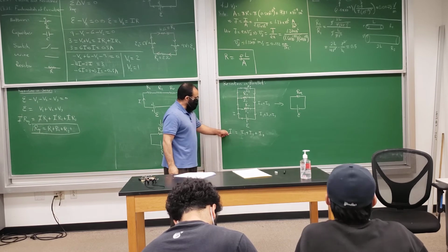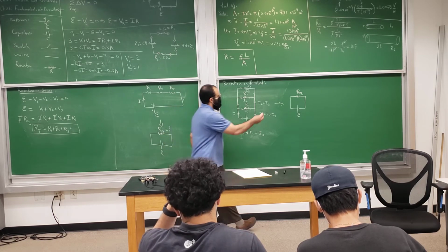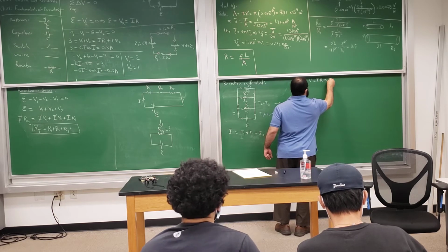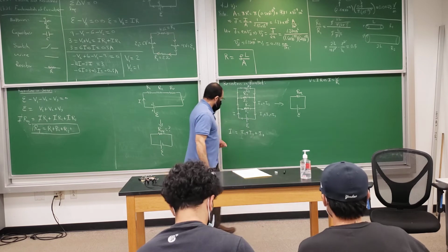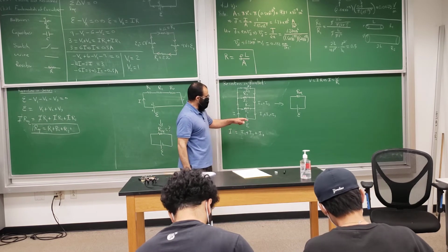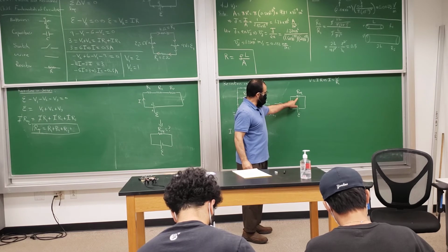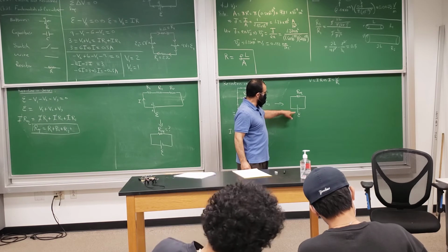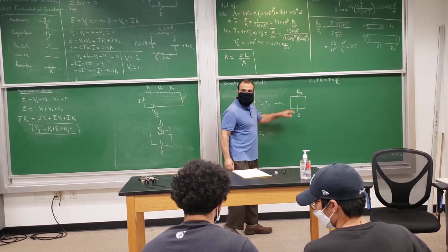Well, I know that V is equal to IR. So I is equal to V over R, right? So for this one, if I were to replace it by just one resistor, the current that flows through it is the voltage across it divided by the resistance. And the voltage across it would be the EMF of the battery. So EMF over R equivalent.